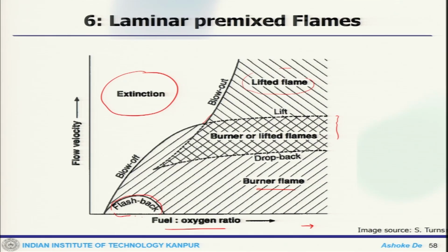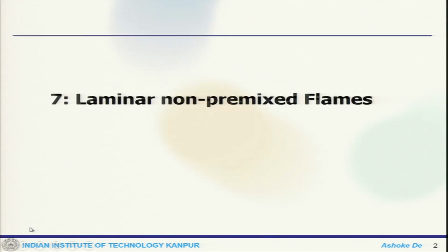So, there are certain limits which these things put on you, and your design should be constrained to these parameters. So, that is pretty much what we wanted to discuss about the laminar premixed flame, and we continue now our discussion on the non-premixed flame. Then slowly we will get into turbulence and the turbulent non-premixed system, because when you go to the turbulent system, all this understanding of flame speed, flame thickness, ignition, flammability limit, blow up, and all this would be required information one has to understand.